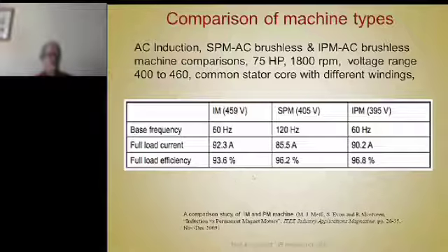They should somehow relate and weight the cost of the copper rotor versus the cost of the surface PM motor versus the IPM, because usually the IPM motor is going to use less mass of magnets than the surface magnet, because it gets a torque component from the saliency between the permanent magnets, which we'll look at later.